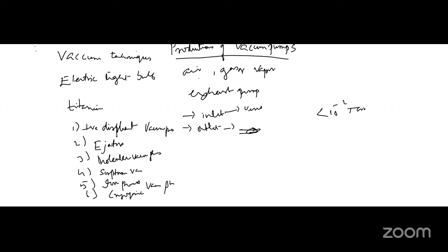Next, we have the cryogenic pumps. In the case of cryogenic pumps, generally, it removes the gas from a container by condensing the gas molecules on an extremely cold surface in the container. So a very low temperature is used. These cryogenic high vacuum pumps create high vacuum by freezing the molecules of air onto a cryogenically cooled surface inside the pump.